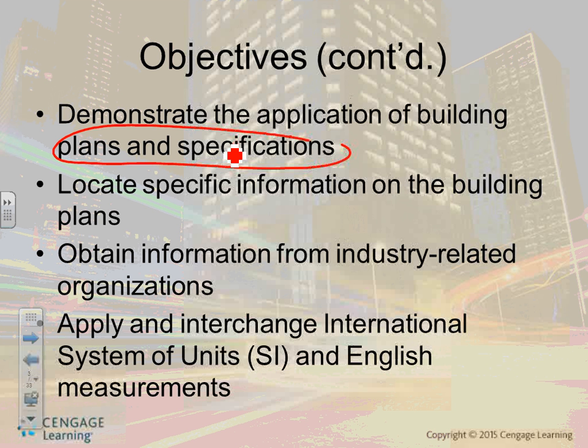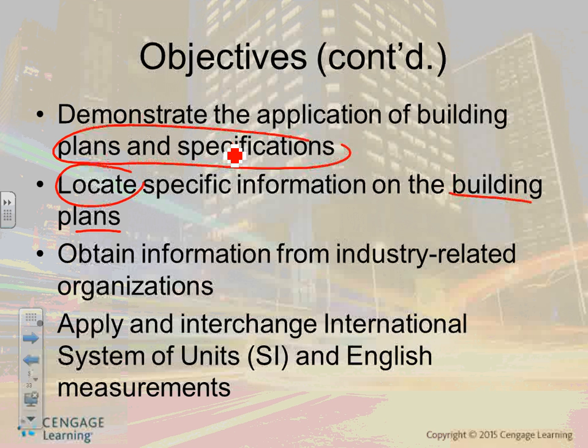How do you locate specific information in the plans? Now, we're not looking at me and saying, well, I'm the one who designed the plans. But guess what? You need to go put a lighting fixture right next to the door. Don't you think you should know the height of the building when you put perimeter lights? So where would you get the height of the building? From the architectural drawing. The first 6 pages here are architectural drawings.